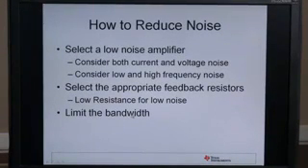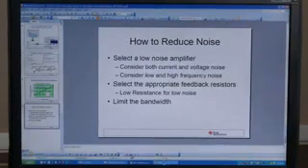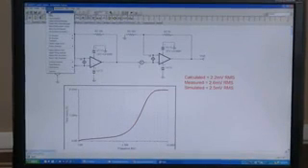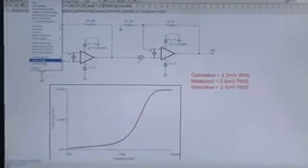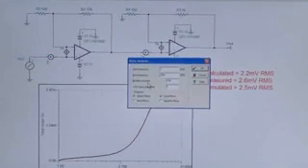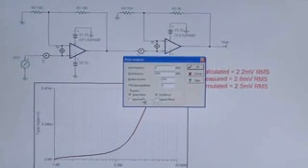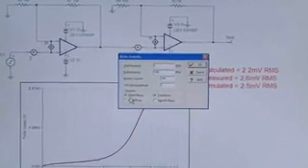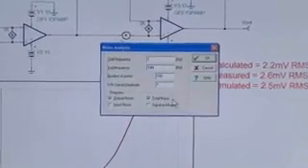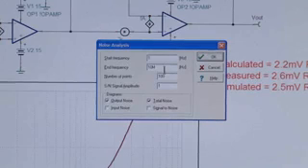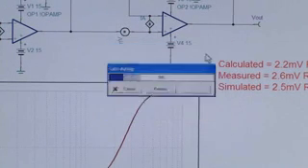Let's do a simulation. We can actually simulate the circuit that we have in our demo here, and it's very simple to do this. We just say analysis, noise analysis, and it has an output noise and a total noise checkbox. Check them both. The output noise will give us the spectral density. The total noise will give us the integrated noise. Set your frequency range to the appropriate range for the bandwidth of your application, a little beyond the normal bandwidth, usually a factor of 10.